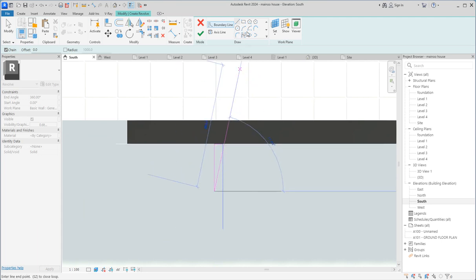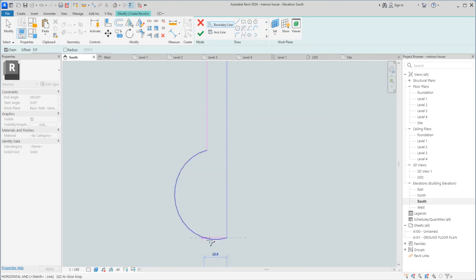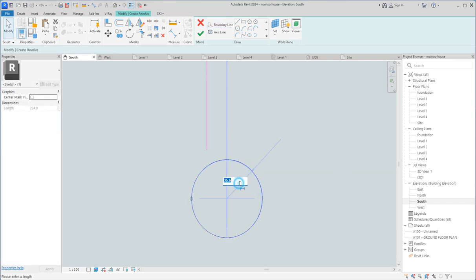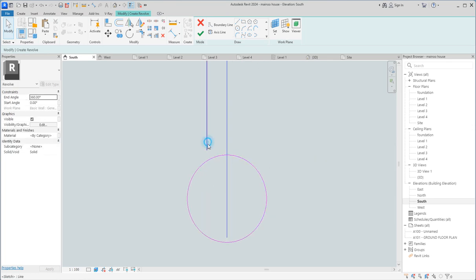Here you can just use the 3-point arc. You do it this way. If it's not accurate with what you want to do, you can decide to change your own style. It's all your choice. I'm deleting this one again. Let me just say I want to use absolute circle. No, absolute circle cannot do this. Can it? Yes, it can. So I think this one is okay. You can increase it to 40. Good. Here I want to draw this down.